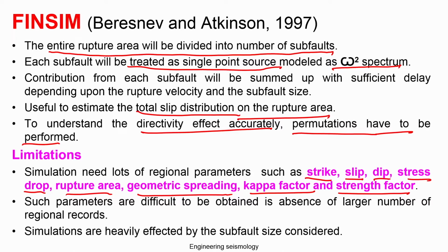Okay. So, the geometric spreading should be obtained from the previous earthquake data. In case it is not there, it is a problem. Rupture area, again, you should have the rupture dimension versus the different magnitudes occurred in the region. Right now, overall in the world, only very few equations are available with respect to rupture area. Stress drop, we have discussed before and after an earthquake, what was the drop of stress. That again depends upon the region, which has to be obtained for different magnitude levels.